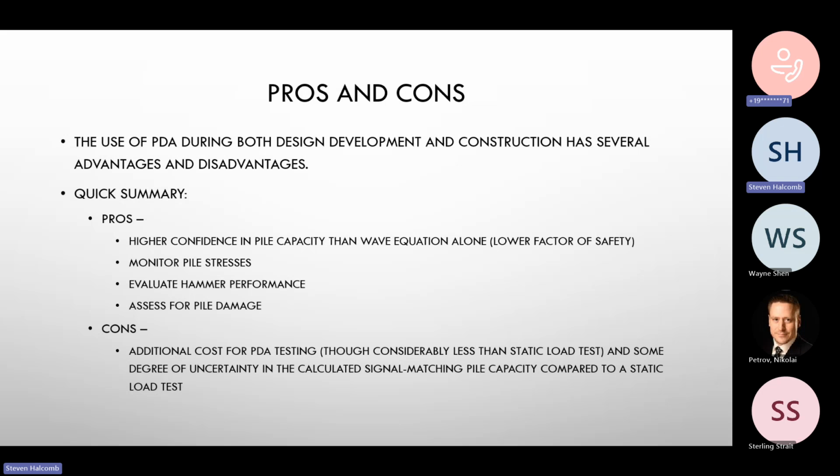Yeah, and the stress is like, you've got these two strain gauges on either side, so each one is measuring the stress. Ideally you'd have the hammer hitting squarely, and the stress is being distributed uniformly down the pile. If you've got a big rock on one corner, it could be concentrating stress there, and when it bounces back on that corner, it'll show you're getting higher stresses in that one corner. Or if the hammer's hitting cockeyed, you're going to be getting it coming down eccentrically on one side. So you can tell if you're getting higher stresses than you can handle.